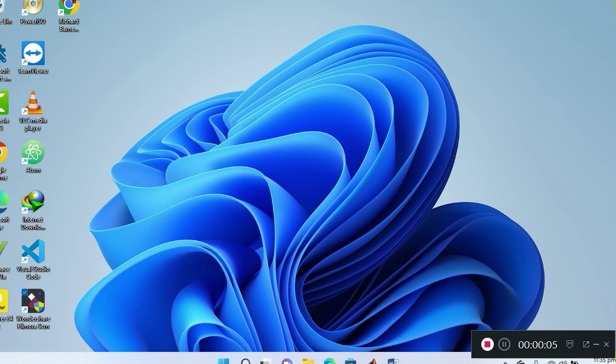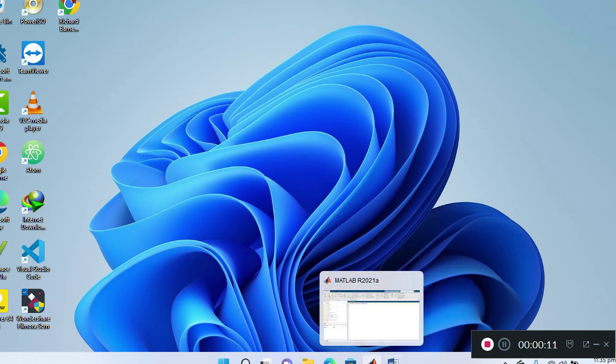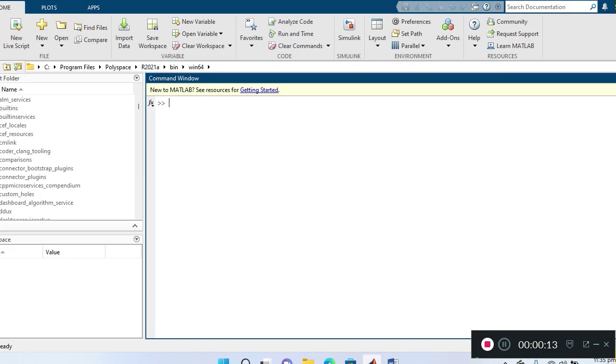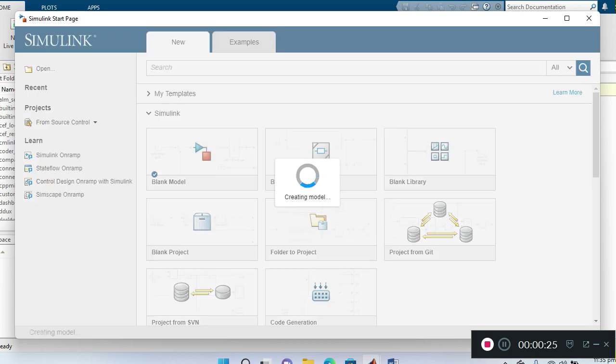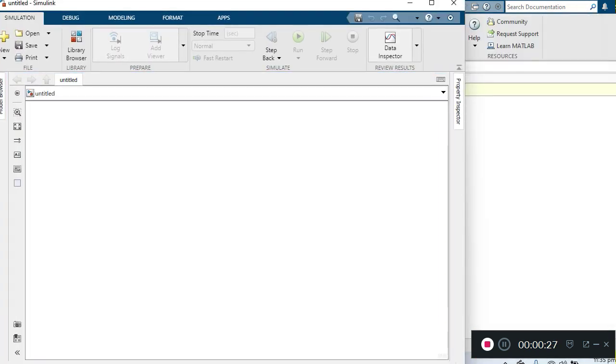Today, we're going to look at the three-phase balanced delta network using Matlab. That is, we're going to use Matlab to realize or verify the three-phase balanced delta network. So we open straight on to our Matlab and we go to Simulink. So in Simulink, we open blank model. So in blank model, we're going to go to library browser.